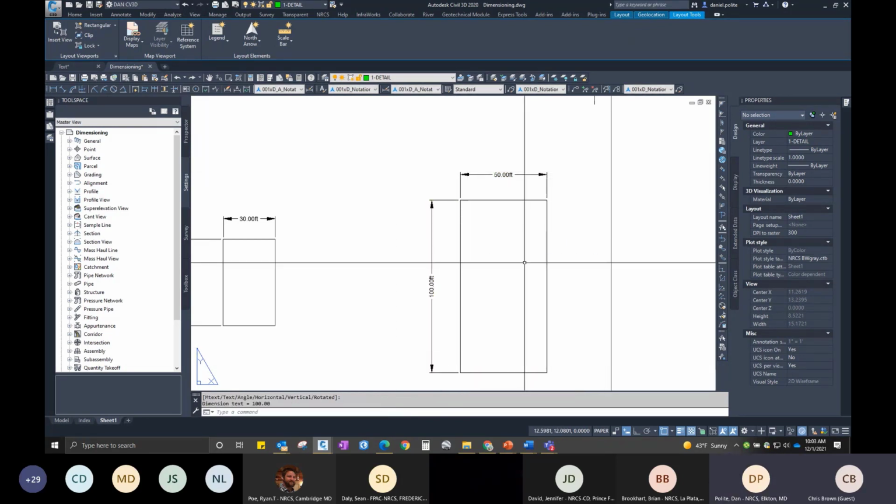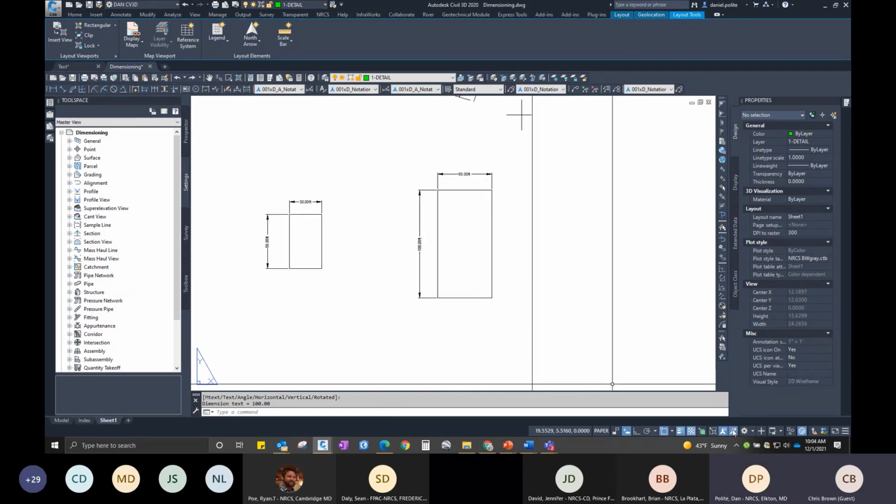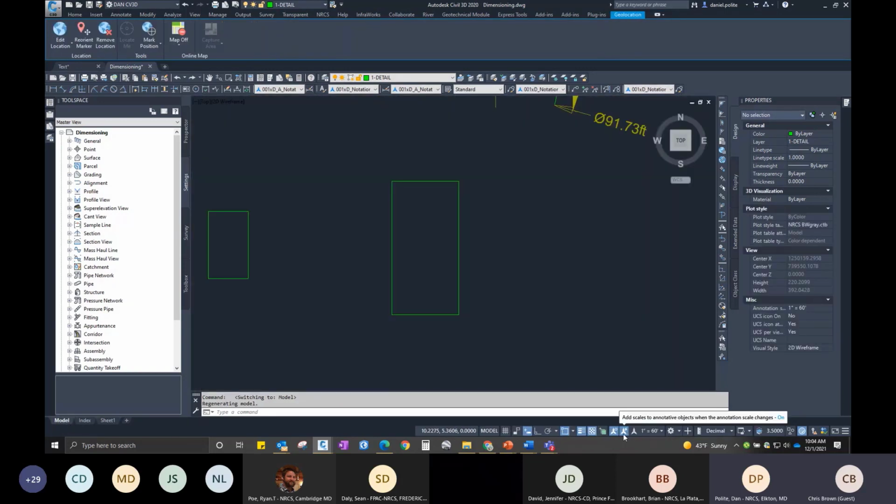by 100. So that's in paper space. It was just because I didn't have this on. So basically what that's doing, again, is making sure that you add all your annotated scales. If your scales are not added up in your model space, if that's not selected, it just throws a wrench into everything. So I always keep both of these on, and I never run into any problems.